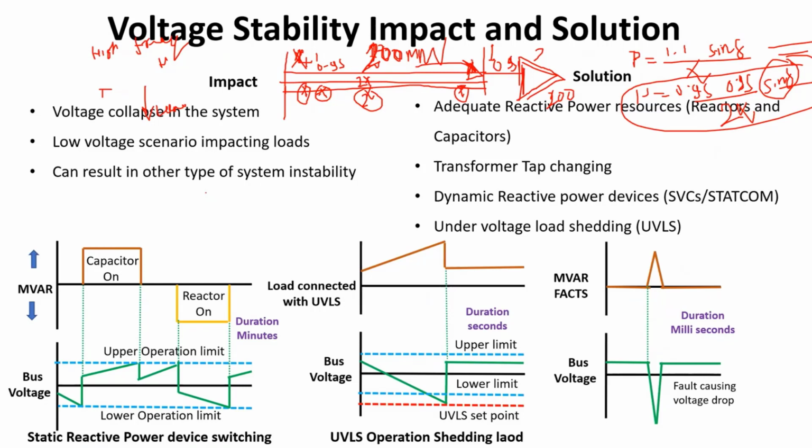So what you can do, whether you will be supplying this load or not, you will be trying to supply this load. How can you do that? One simple thing is that I'm not going to feed this 200 megawatt of load because it is crossing my limits. N-1 is not stable during the n-1 operation. If one line trips, then my entire system can collapse. So I will not supply this additional 100 megawatt. Even if it comes, I will keep it out. But that's not the practical case. You have to supply that amount of load, right?